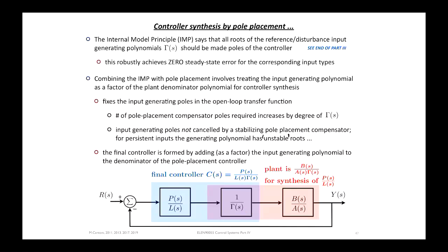If this is a sinusoid of frequency 1, we know that in order to get zero steady state error, the open loop transfer function will have to have poles at s equals plus j and minus j. So let's force it in there if we know that's what we want to achieve in steady state: zero error for a sinusoidal input. Then you can place the closed loop poles by absorbing this fixed thing that you've inserted into the open loop to ensure satisfaction of steady state specifications.